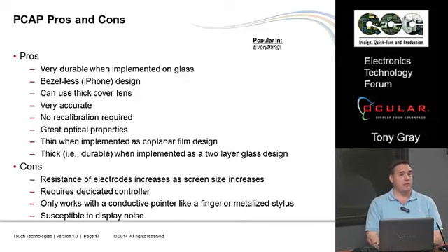It's extremely accurate because of the layout of the electrodes and because of the interpolation and the very precise measurement of the individual capacitor values. You can actually get very accurate with these touch screens. A lot of the touch screens that we produce are accurate to, say, within 1 or 2 millimeters, while a typical finger is 8 millimeters, so that's basically an eighth of the size of your finger. And some of the consumer products, which have really tight electrode spacings, are even better. There may be a half millimeter, 500 micron kind of accuracies.